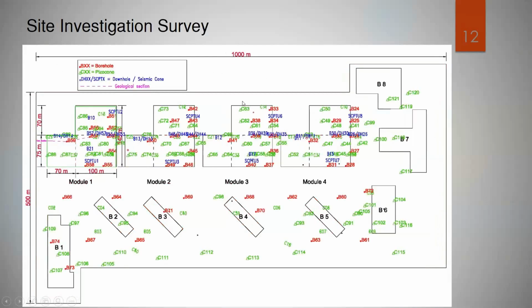Actually, the site has an intensive site investigation survey. We have in-situ testing like SPT, 75 SPT, and 124 CPTU, and we have also geophysical tests like 12 downhole tests and 8 seismic CPT. Also, we have intensive lab testing: index properties, oedometer tests to get the pre-consolidation pressure, and unconfined compression tests and UU and CU triaxial tests to get soil shear strength.